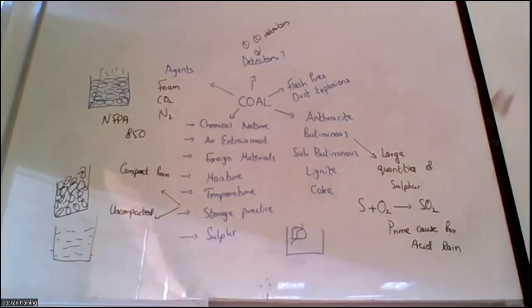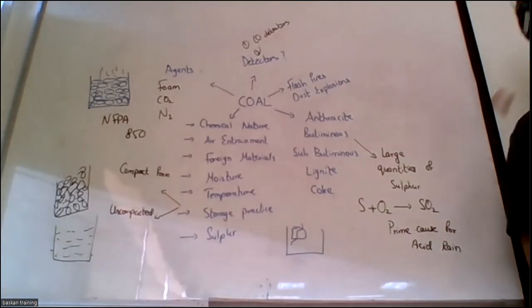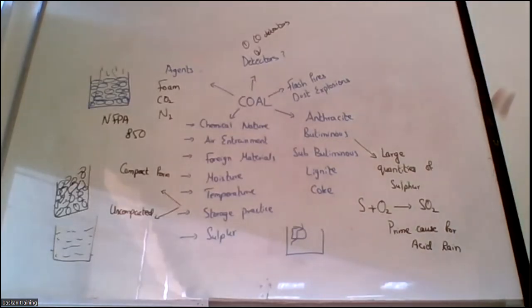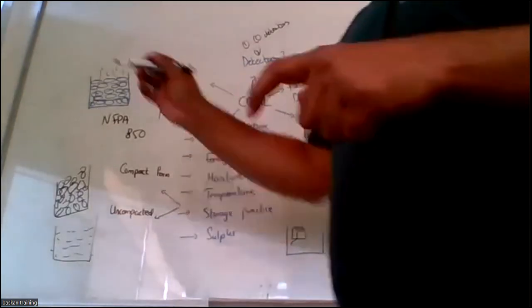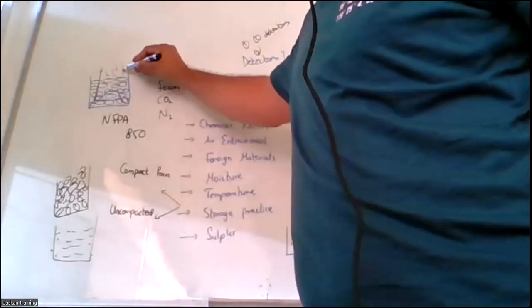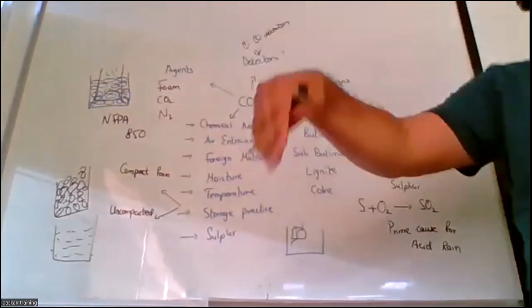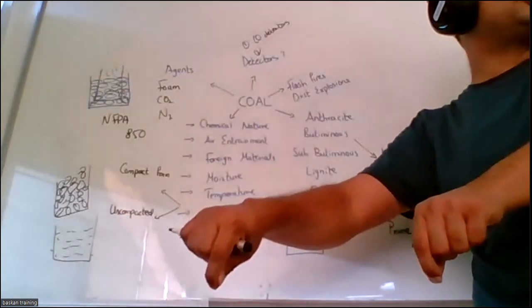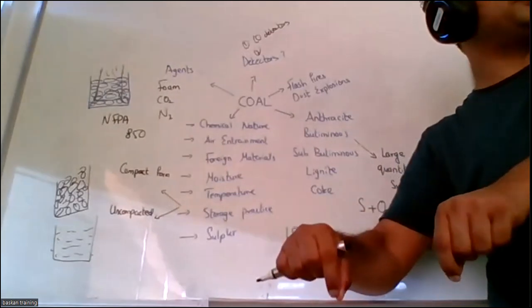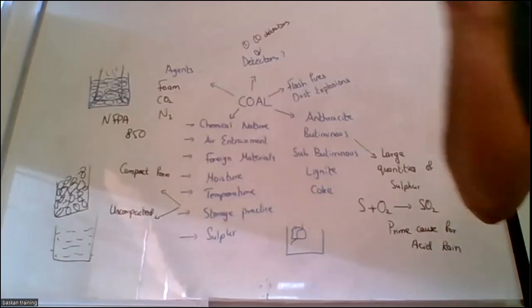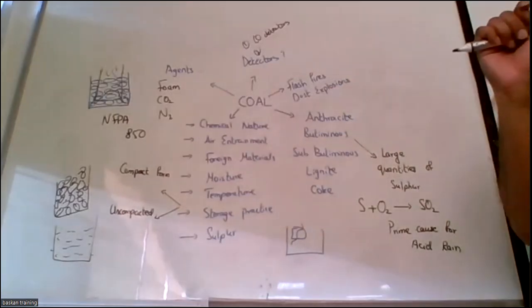Linear heat is one of the most appropriate answers. We use linear heat detectors. One example of a linear heat detector is the thermocouple. We use thermocouples that are approximately 3 feet long, and we place them at the bottom of the coil. So when the heat rises at the bottom of the coil, we get an indication from the thermocouples.